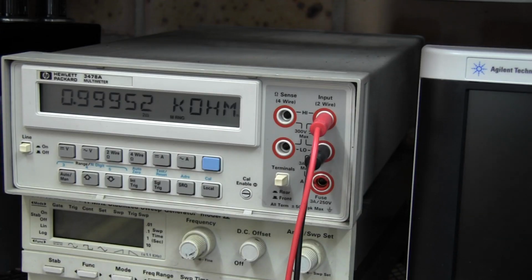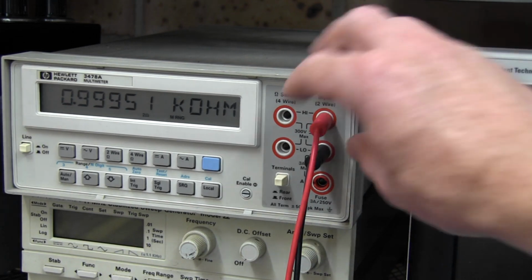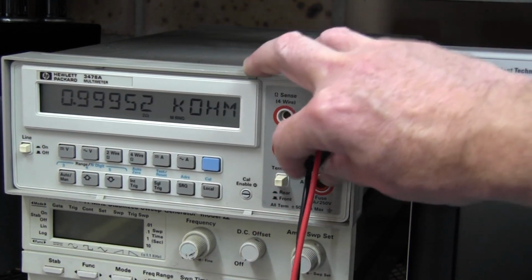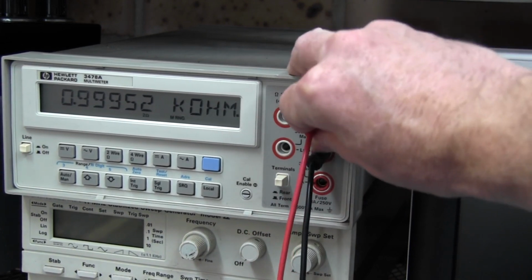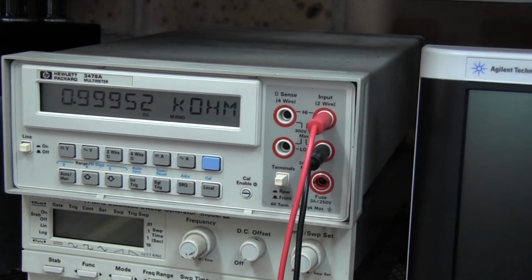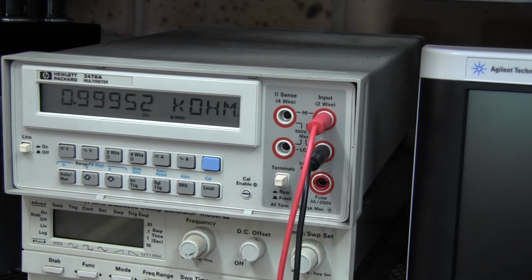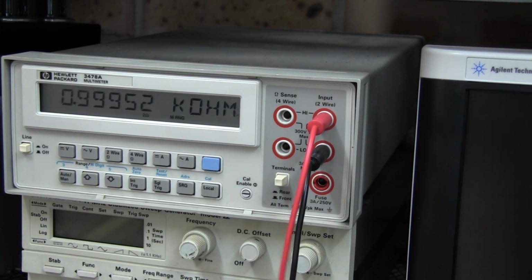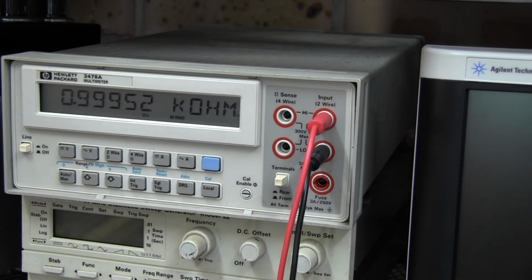And there's our first resistor in this batch here. I've left it for a while, and it really hasn't varied much at all, plus or minus at most 2 least significant digits. So I'm fairly happy with that. I've played around with the probing, and I've swapped it around, and I've also got it on fixed manual range here, so it won't auto range or anything like that.